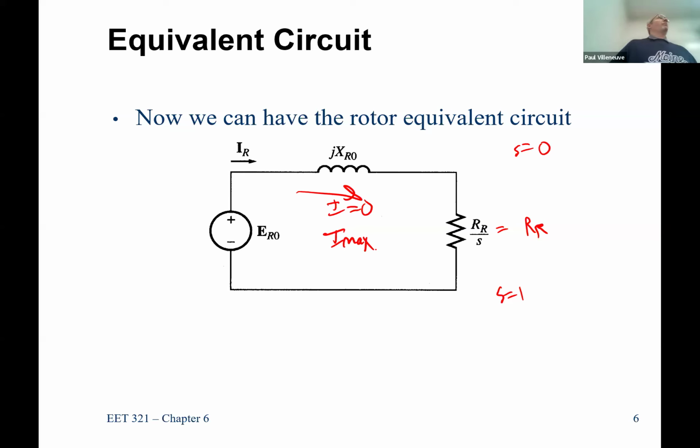Let it burn, basically, is what the National Electric Code says. Keep that fire pump running. Do not let it trip offline, because even if it's going to get damaged, it's still better to replace a damaged fire pump than it is to let the building burn to the ground, I guess.